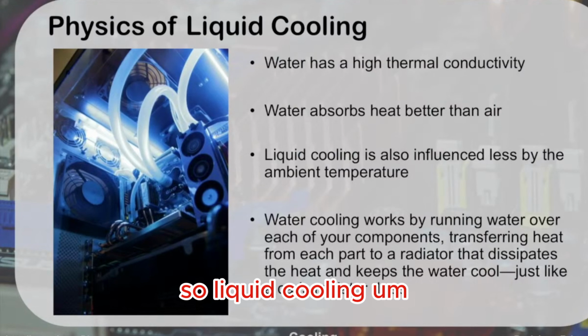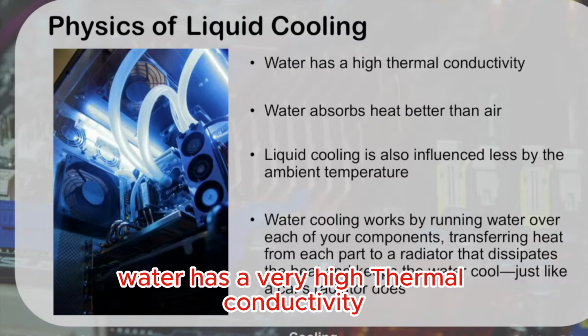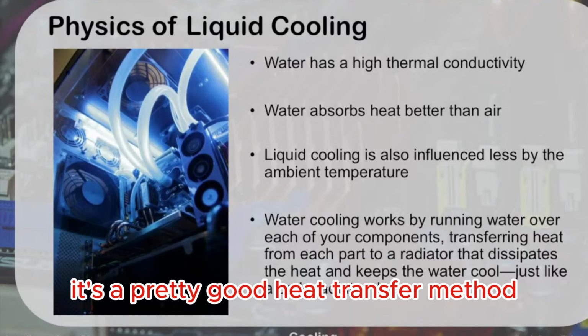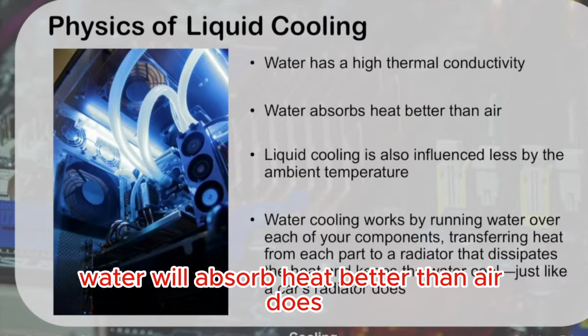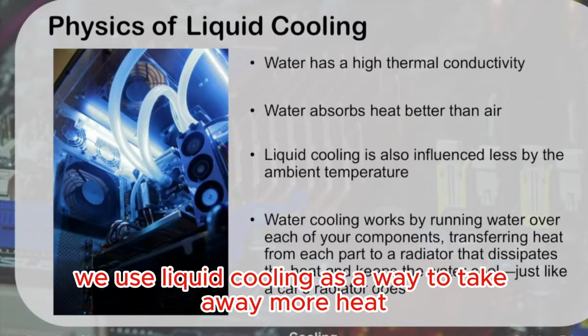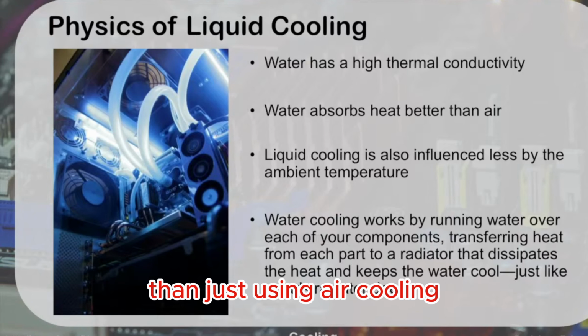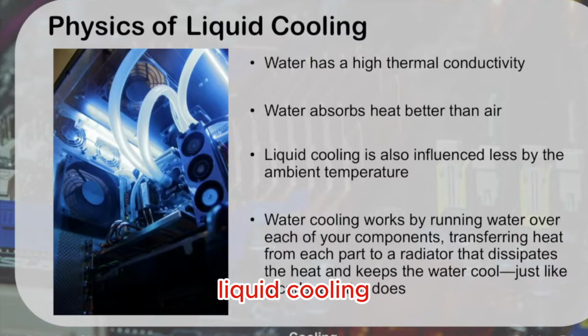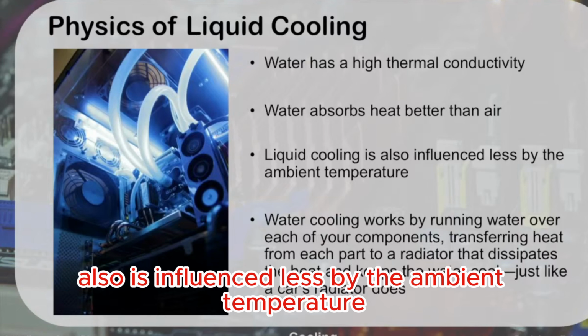So, liquid cooling. Water has a very high thermal conductivity. It's a pretty good heat transfer method. Water will absorb heat better than air does. So we use liquid cooling as a way to take away more heat than just using air cooling. Liquid cooling also is influenced less by the ambient temperature.